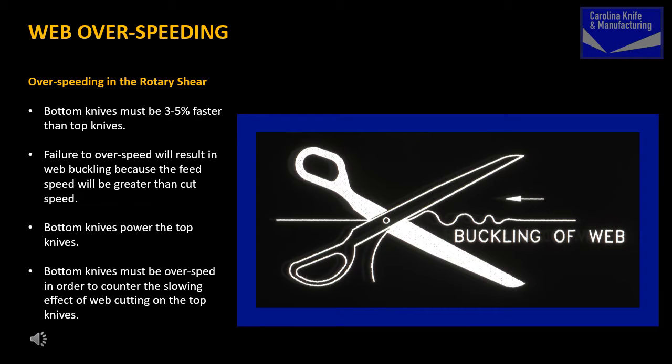As mentioned, the dynamics of a rotary shear used in paper, film, or foil web separation is very similar to the dynamics that exist in a pair of household scissors. In order to make the scissor cut, pressure must be applied to the handle to make the cutting edges come together at that one intersecting cut point. This point is never at the tip of the scissor, but deeper back in the throat of the scissors. The same elements that enable the scissors to cut, where the two cutting edges come together optimally, are necessary and must exist in any efficient shear slit setup.